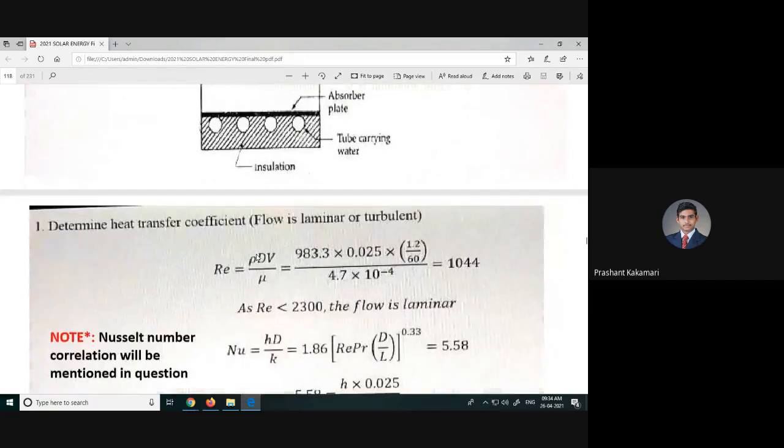If you understand this problem, the heat is carried away by water, but at what speed, and whether it is a forced convection or a laminar heat flow? For that also we can use the Reynolds number first, to decide whether it is laminar or turbulent flow, or a natural or forced process. In that case, the Reynolds number will give us the clear picture.